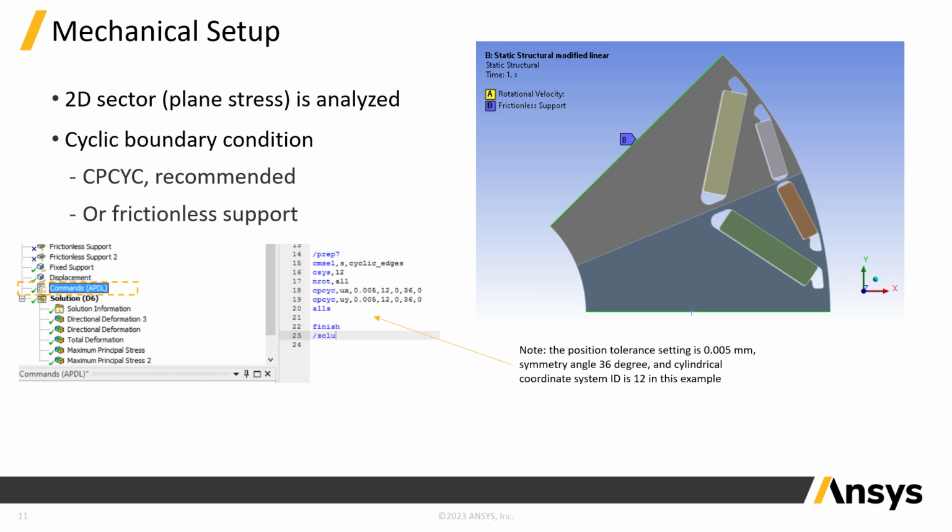Or if you're in the design iteration stage, you can simply approximate it as a frictionless support, which is more rigid, but gives you similar results before the final validation stage.